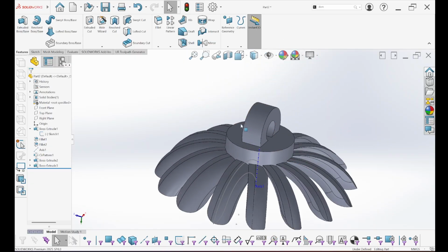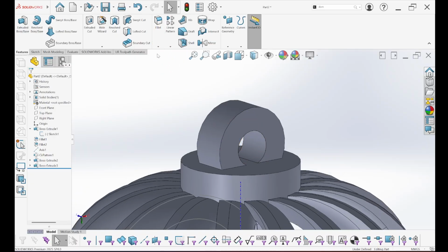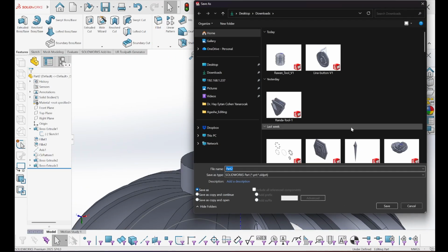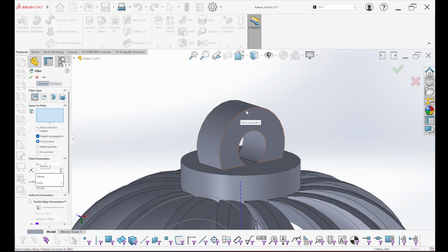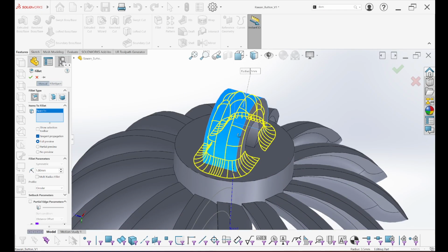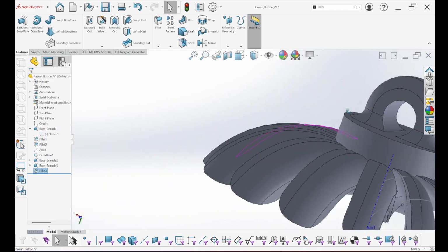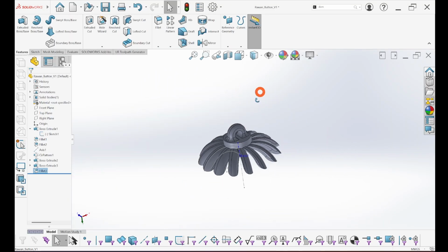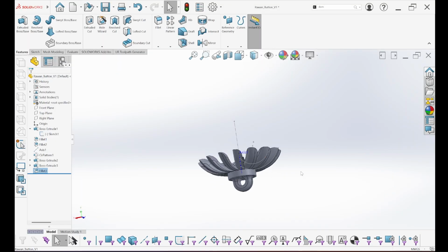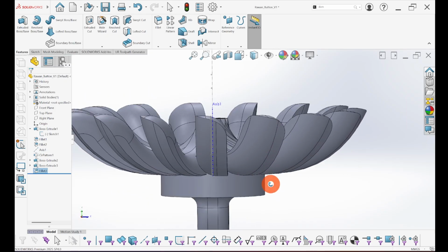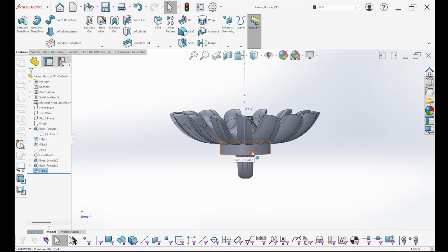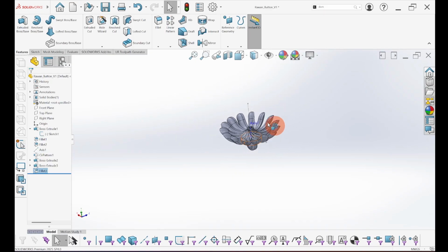Now, what I can do last is soften the edges on that loop. Save first. So I'm going to name it button. We should have saved before that. And fillet 1 millimeter. If you click on this, you see it's trying to fillet everything. If you like it, then you're finished. It's possible that Itamar is going to advise to cut the product around that line. This way you have 2 flat surfaces to print, and we can then glue them with a 3-second glue.